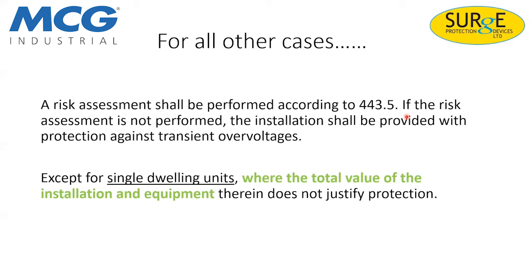For all of the cases, a risk assessment shall be performed according to 443.5, which I'm going to go through in a moment. If the risk assessment is not performed, the installation shall be provided with protection against transient overvoltages, except for single dwelling units, so our domestic installations, where the total value of the installation equipment does not justify protection. So that's what we've got to consider.